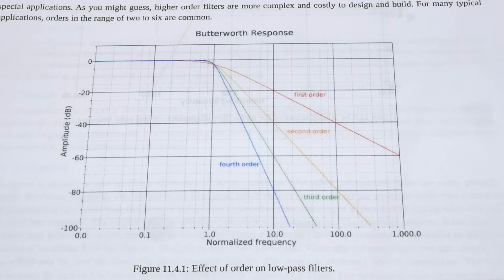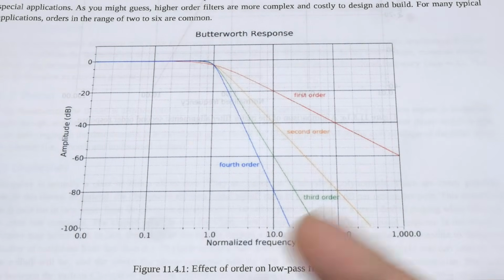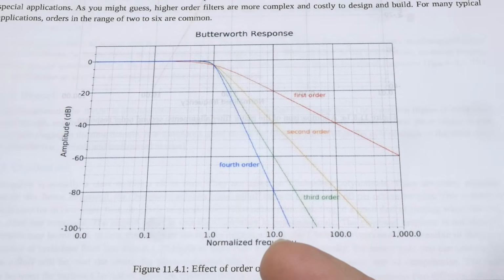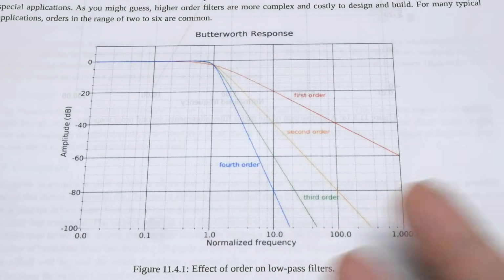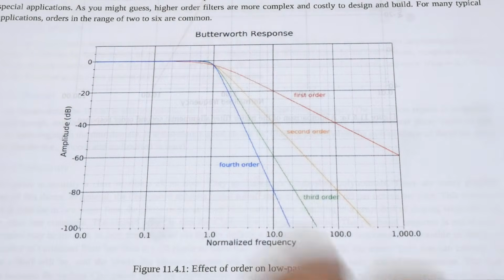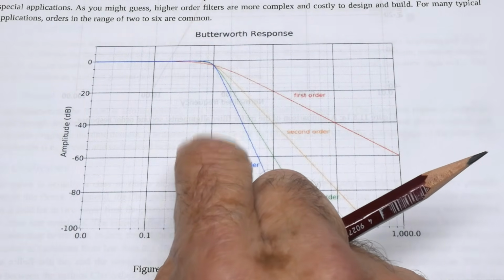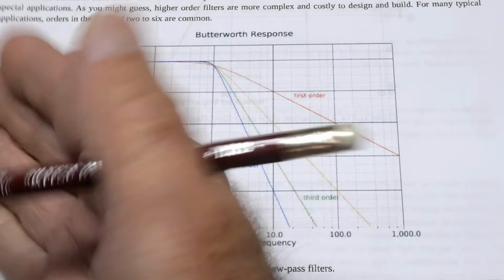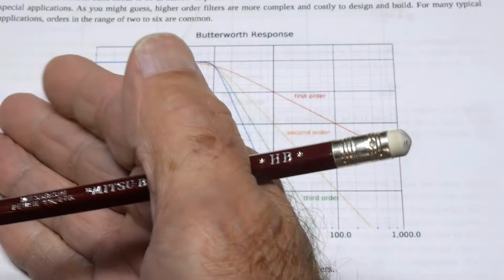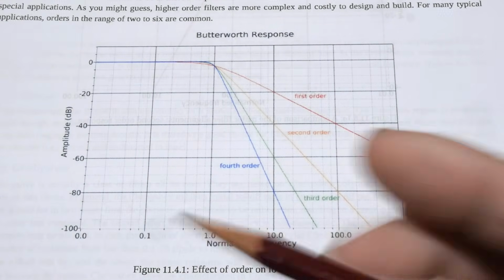All right, let's talk about filter order. You may hear that. In fact, yesterday, I kind of glossed over it when I was looking at orders in order to match the filter that we had. I just kind of typed it in knowing what it was, but we'll talk about how you can determine what order you need. The first thing about order is basically it's almost like amplifier stages. If you had an amplifier with a first stage and a second stage and a third stage, imagine a filter with a first stage, a second stage, and a third stage. And each stage makes it roll off faster.